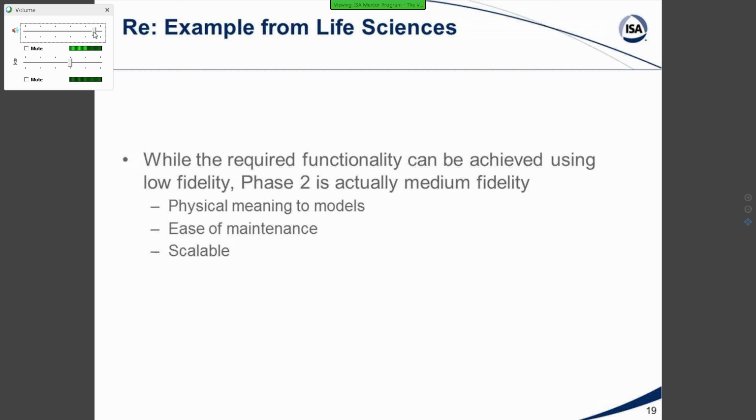If they were to de-pipe a valve, you don't have to dig through your code and remove conditional statements from here and here and tweak your calculation there. You just tweak your process model to route through a different valve or bypass a valve. So it's much easier, and it's easier to scale at that point as well. You can do pieces of it at a time and go to a much higher fidelity as necessary. So maybe if you wanted to do a bioreactor, you can add this to your infrastructure that is in place.